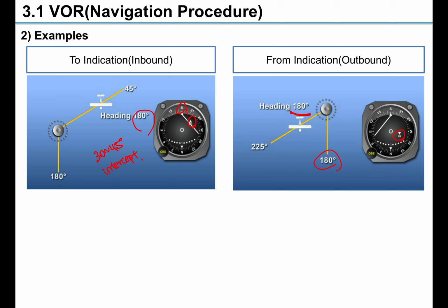So some instructors will tell you that to correct this off course, turn toward the needle, and I recommend you check the azimuth of the needle location. So I will turn heading about 210 or 240, and I'm going to turn toward the 150 or 120 depending on the type of aircraft you're flying or the distance from the VOR because of the sensitivity, or how soon you have to intercept the radial.